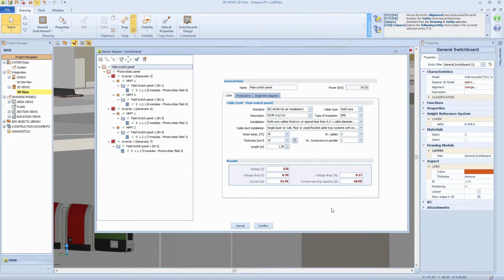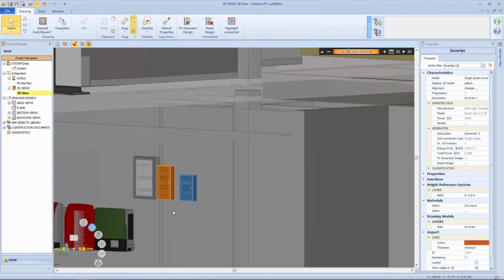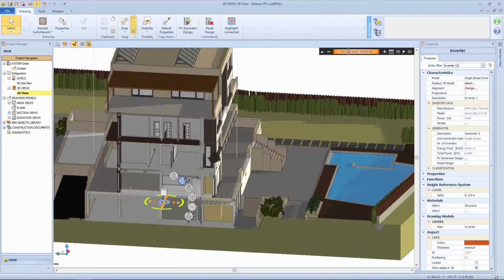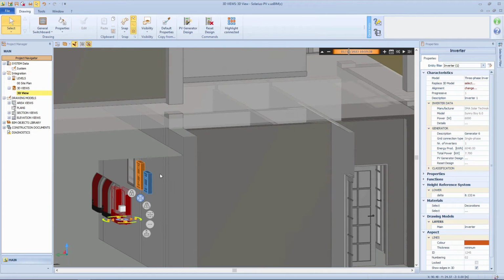The software also allows dynamic updates. For example, if you change the cable length, the voltage drop calculation result is updated in real time, and the tool will also alert you in case of incoherent values. Use the calculator tool to check and determine the minimum cable section required to keep the voltage drop within the maximum limit. Having to deal with multiple separated systems, it comes in handy to have a function that highlights the connections between the systems and their generators.